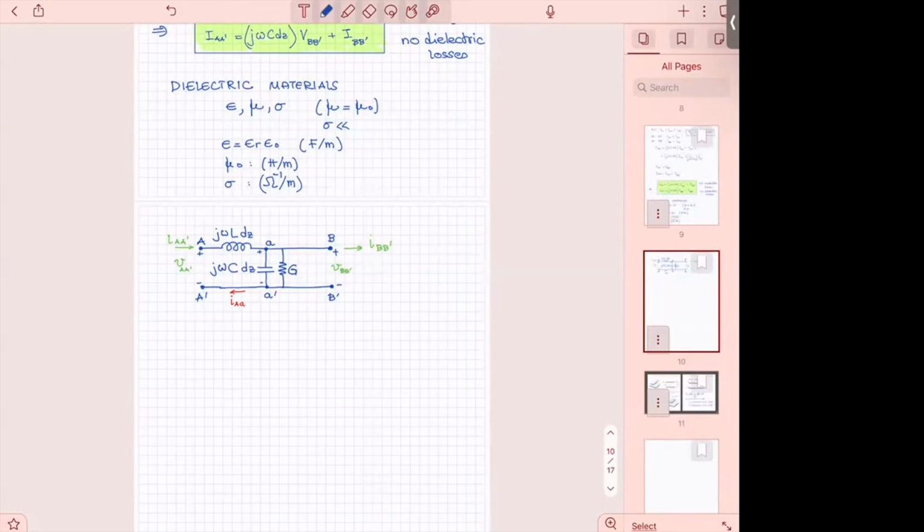That's why a lot of times when you see resistances in parallel, you indicate them with a conductance G. Because practically you use the inverse of the resistance, and that allows you to sum this term to this, right? In series, though, a resistance is shown as a resistance. Why? Because in series, resistances are summed up. So it's only for simplification of the formulas, right?